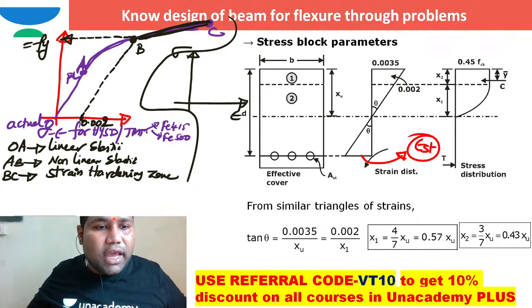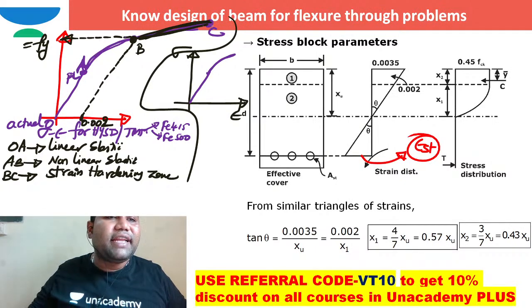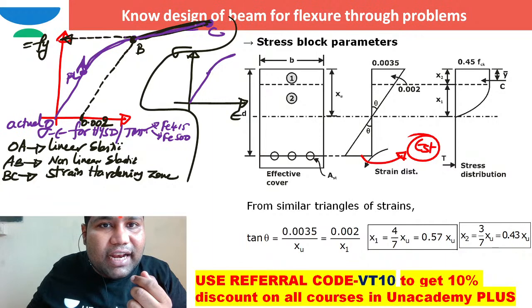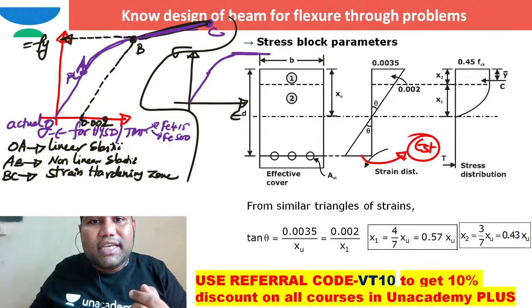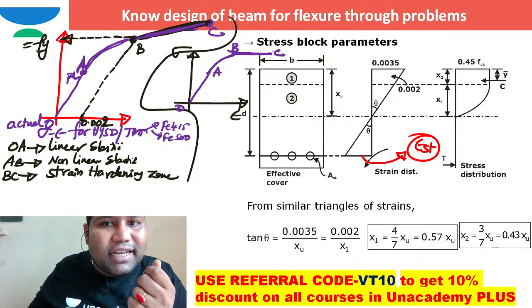So definitely I can show, from O to A, here also O to A, from A to B it is curved, from B to C I am generally neglecting the strain hardening zone. When I neglect the strain hardening zone, instead of an inclined line, I can take that BC zone as a flat zone. This is the idealized stress strain curve. This is B, this is C, this is A, this is O.